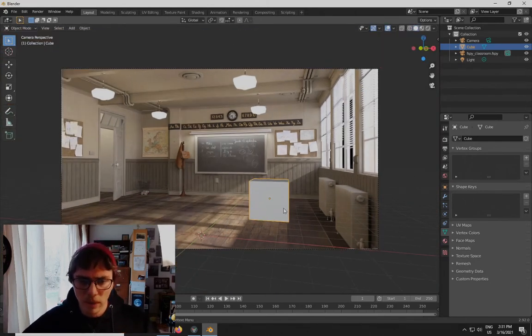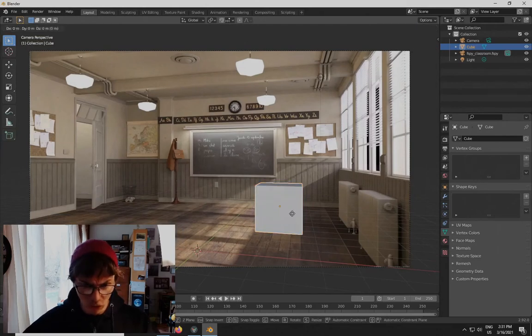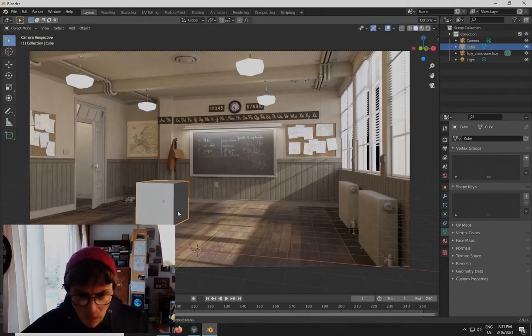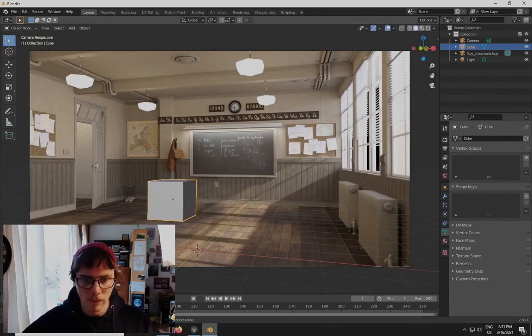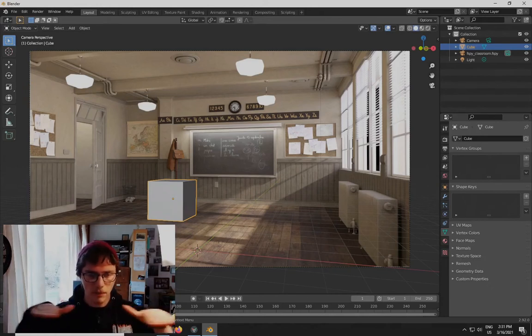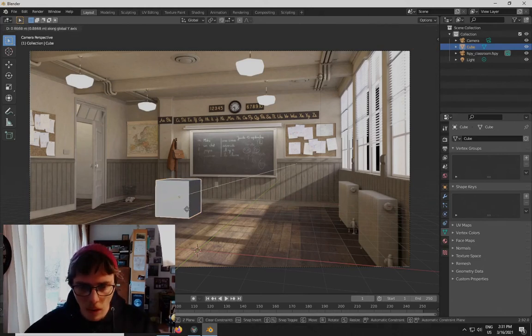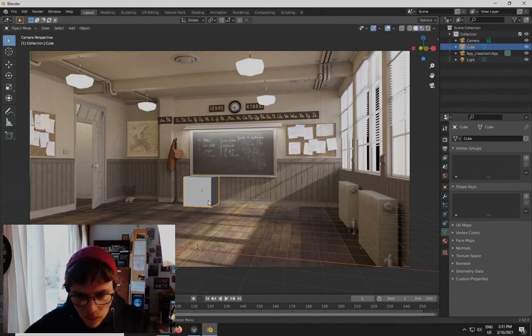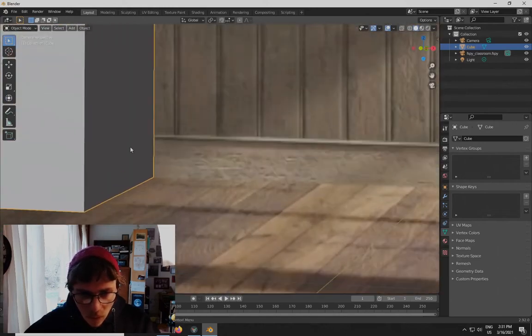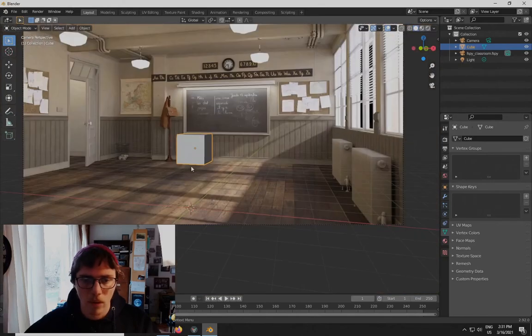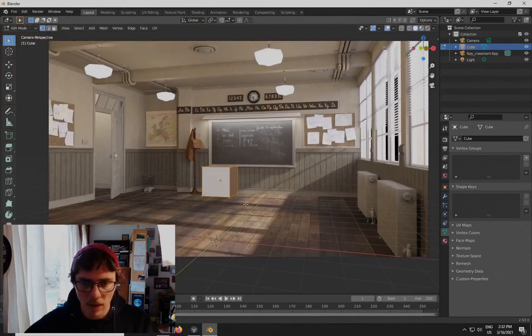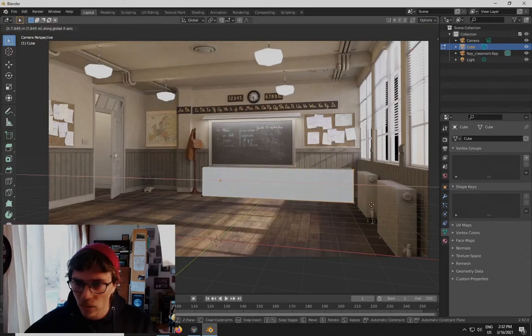Having the cube there is convenient because I'm actually going to turn it into our room entirely. So this bottom face of the cube is already on the floor. That's great. I'm going to keep that cube aligned with the floor, push it back to the wall until it feels like it's lined up with the wall. And we'll have the chance to adjust this more. Great. I'm going to tab into edit mode. You could do all this with scaling outside of edit mode.